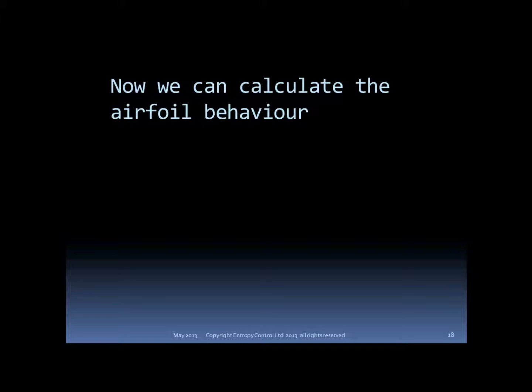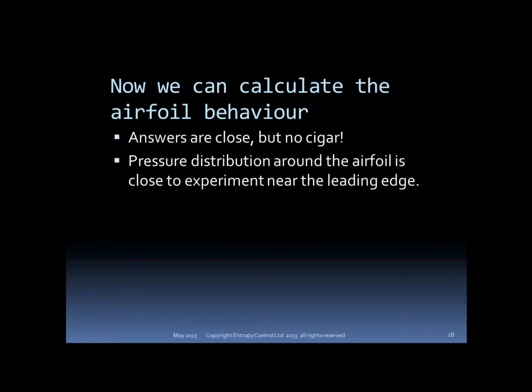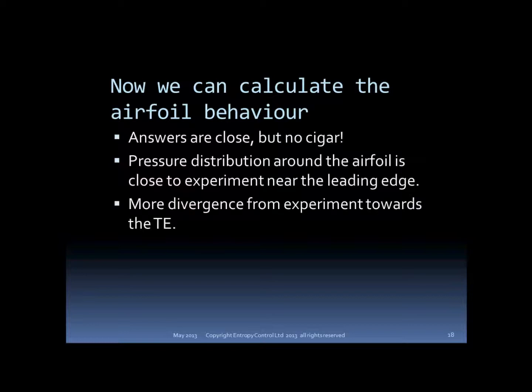So the first question from the engineers is, does it work? And the answer is close but no cigar. The pressure distribution works very well near the leading edge, and it doesn't work quite so well near the trailing edge. And of course, the solution has zero drag, which would be great if it was true, but it's unrealistic.